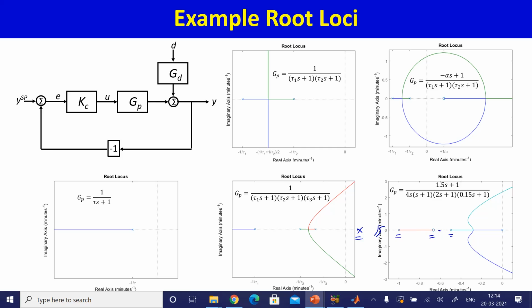And then you do a 60-degree curve this way and a 60-degree curve that way, and because you break out and then the asymptote is actually quite far away, this asymptote acts as an attractor, and then you get this curvy behavior. Okay, and this curvy behavior is coming because of this 0 and the pole that is very far away.